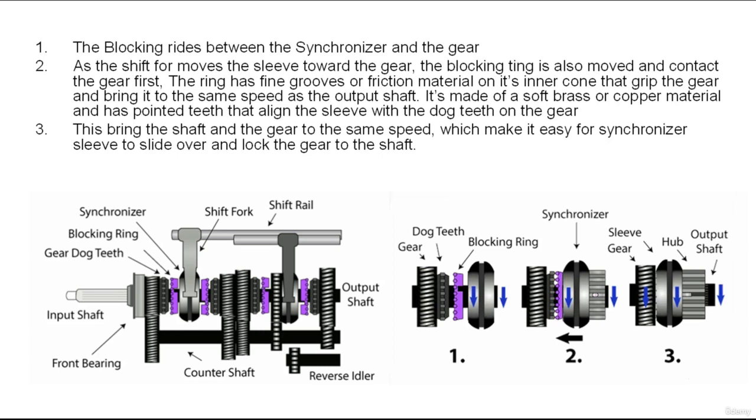To disengage the first speed gear from the pinion shaft and shift into second speed gear, the clutch must be disengaged as the shift fork is moved to pull the synchronizer sleeve and disengage it from the first gear. As the transmission is shifted into second gear, the inserts again lock into the internal groove of the sleeve. As the sleeve moves forward, the forward blocking ring is forced by the insert against the cone friction surface on the second speed gear shoulder.